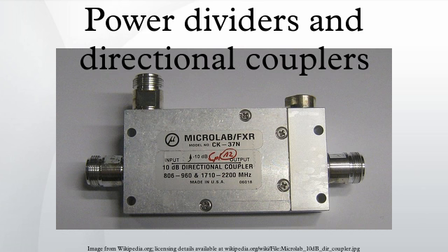A representative example from Figure 21 is shown in Figure 22. Note that there is an additional fixed 90-degree phase shift to both ports at each combiner divider, which is not shown in the diagrams for simplicity. Applying in-phase power to both input ports would not get the desired result. The quadrature sum of the two inputs would appear at both output ports, that is, half the total power out of each. This approach allows the use of numerous less expensive and lower power amplifiers in the circuitry instead of a single high-power TWT. Yet another approach is to have each solid-state amplifier feed an antenna and let the power be combined in space or be used to feed a lens attached to an antenna.